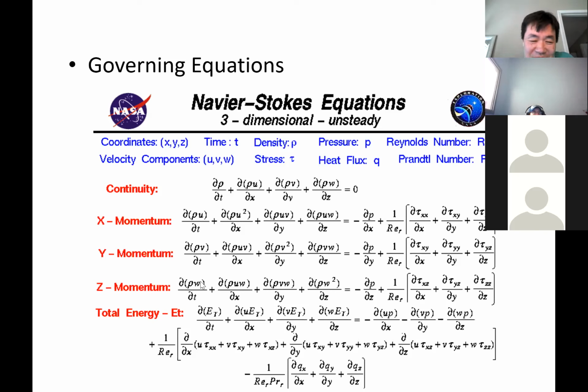Okay, partial differential equation. Look at this: 3-dimensional, unsteady. The partial time term is there, right? 3-dimensional, and also nonlinear. Look at the velocity terms, uv, uw. These unknowns are together in the derivative, so it's nonlinear. So no way you can solve this analytically. The only handful of practical problems you can solve using this equation are under heavy assumptions. If you have a lot of assumptions, then you can remove many of the terms here, so it becomes a simpler form of the differential equation that you can solve. But it's very, very limited. Only a handful of problems can be solved.